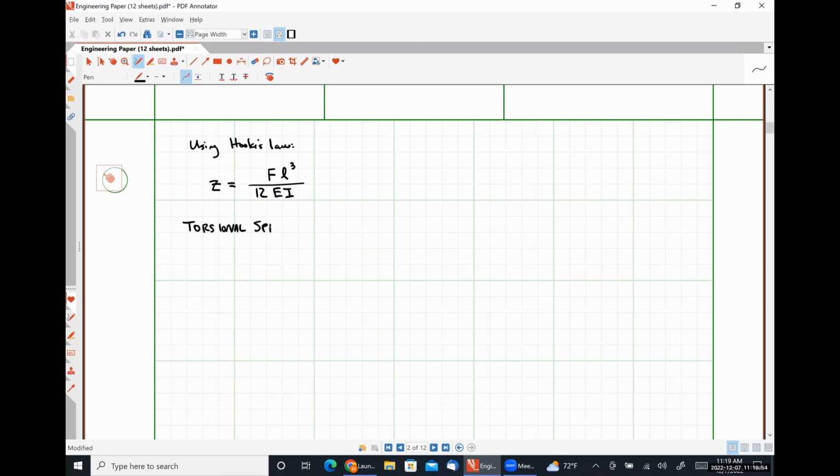All right, now our last spring: torsional springs. All right, so the springs that we've dealt with to this point give us linear displacements. A torsional spring is designed specifically to give us some sort of angular displacement. So if we think about how the TI digital micro mirror devices work that we talked about on, I guess it was the second day of class, might have been the first day of class, we saw deflection of plus or minus 12 degrees depending on how the array was actuated. That has to be carried out by a torsional spring because we want rotation of the microstructure, not deflection of the microstructure, okay?